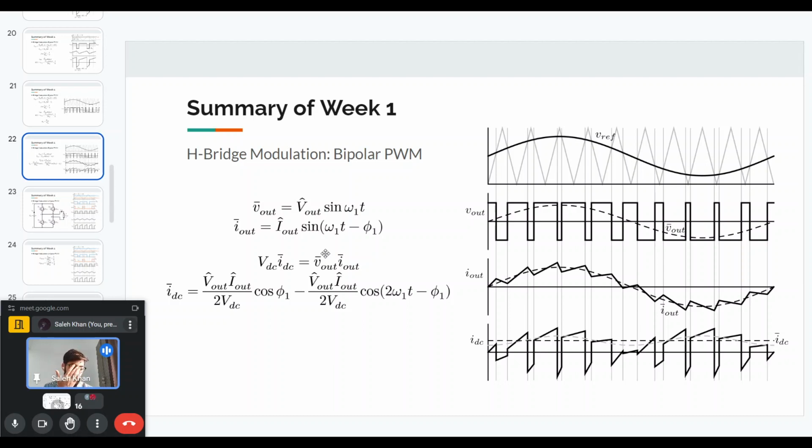But we may want to have some safety factor, and that depends on the application. If you are expecting any fluctuations in the output or the input, you can have a safety factor. So even though the output voltage and current is only, let's say, X amount, you can have 1.5X times the inverter rating, so in case there is any extra load for some duration, the inverter should be able to handle it. But that depends on the particular application and the different cases for which the inverter will be used.